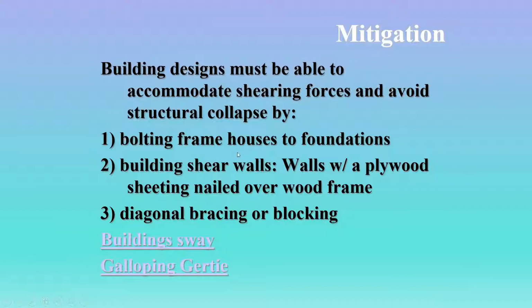So in areas where there's a lot of possibility of ground shaking from earthquakes, adding a sheet of plywood before you put in the drywall helps to rigidify the whole structure. If you think about it, you get one of those really cheap bookcases from the store, and you put it all together, and then the thing's all wobbly until you put that little cardboard piece on the back.